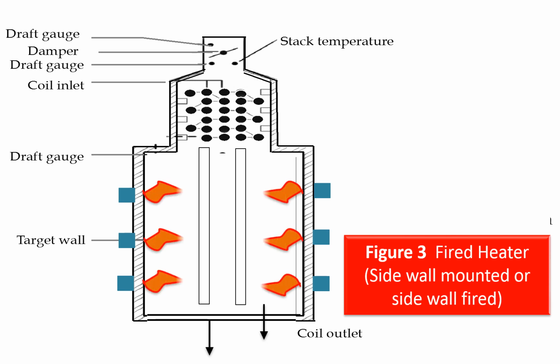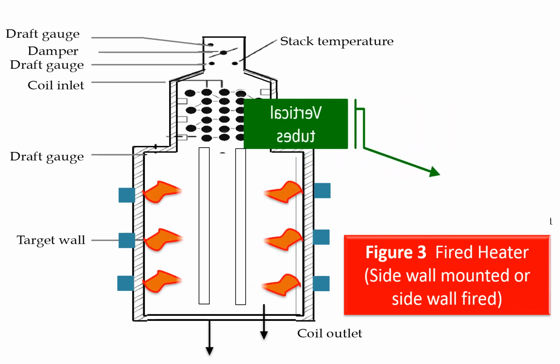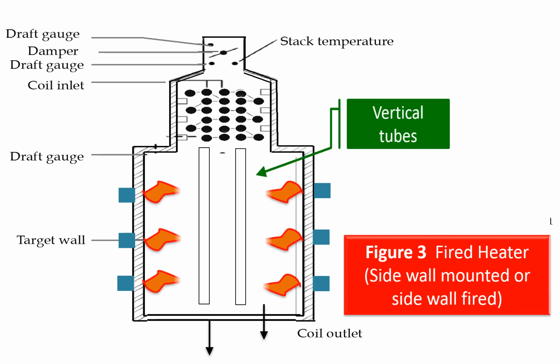This figure is an illustration of wall-mounted type fired heater. The three burners shown are mounted on the wall, opposite to each other, for even heat distribution. Here again, the number of burners is decided by the heat duty. Multi-level wall-mounted burners are required for large heaters.